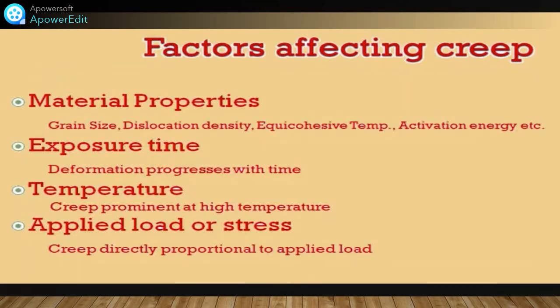This rate of deformation is a function of various parameters, which are as follows. First, material properties like grain size, dislocation density, equicohesive temperature, activation energy, etc. Second, exposure time. Third, temperature. Fourth, applied load or stress.